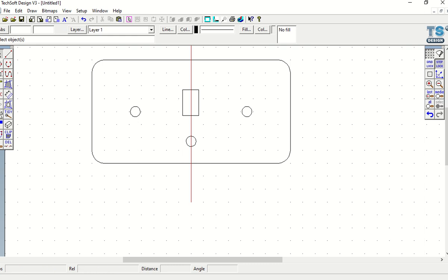Sorry about that. Right, now, I want to attach this to the housing behind with some screws, and the holes for the screws need to be 3 millimeters. So what I'm going to do is put my screws in here, and this, of course, pay attention, is 10 millimeters by 10 millimeters in from the corner.